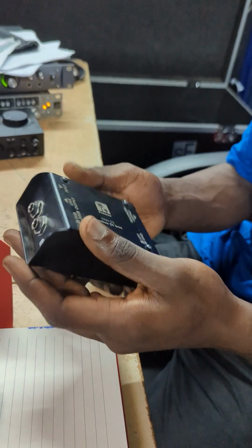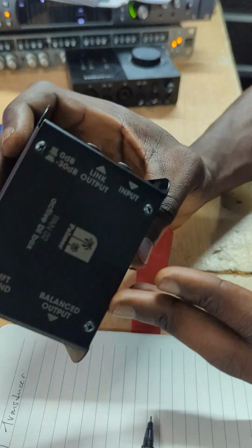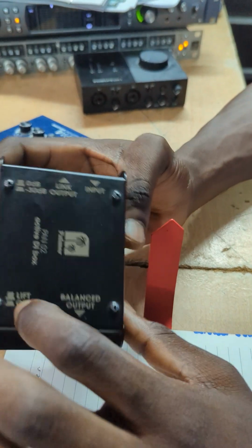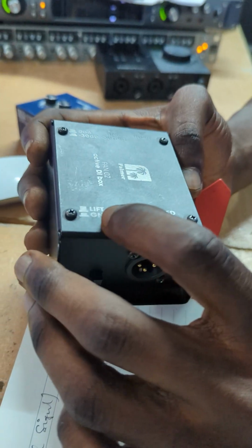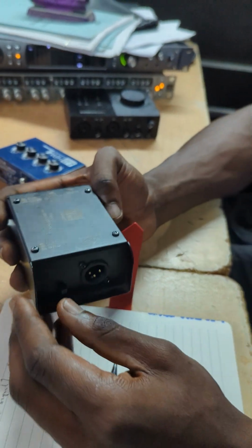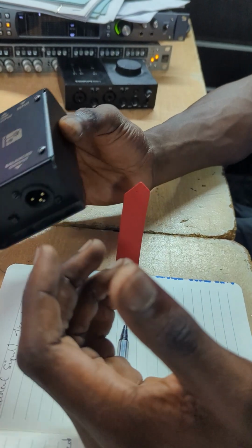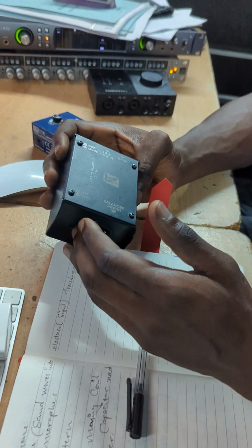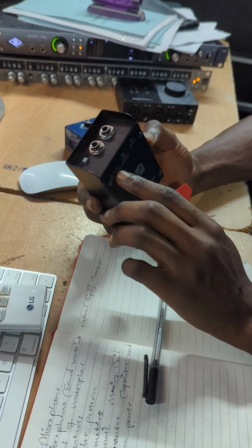So here we can see that a DI box also has parameters which we need to consider talking about. First of all, we are going to talk of this ground lift, which is a button here. The ground lift is used to lift the ground in a signal, and when you press this button, it means the ground is going to be lifted in that signal, and hence this DI box is going to reduce noise in that signal, if at all that noise is coming because of the ground. And here we have the pad.